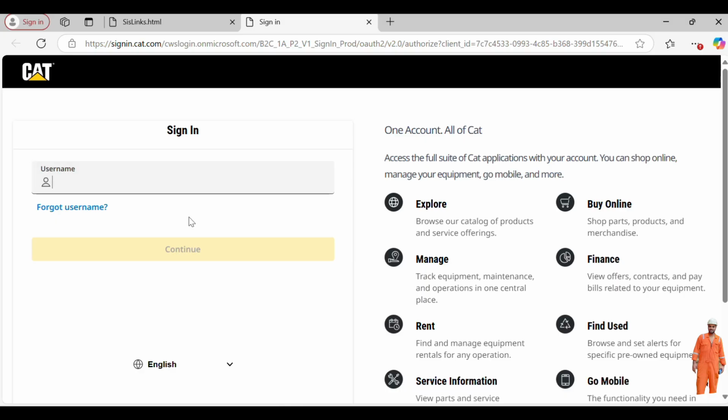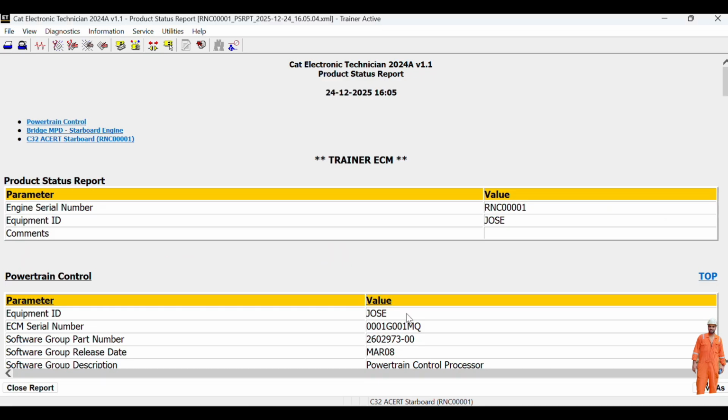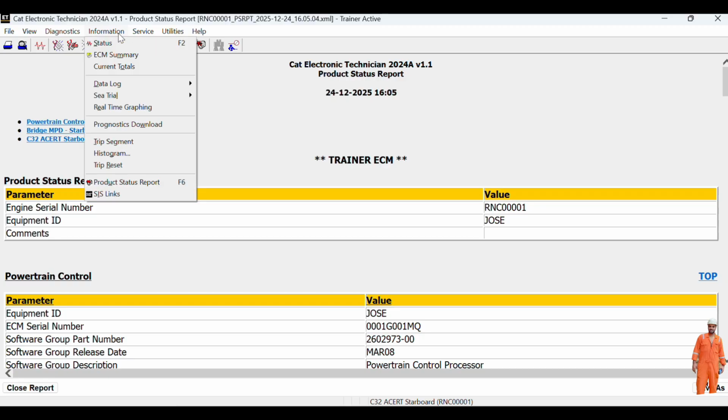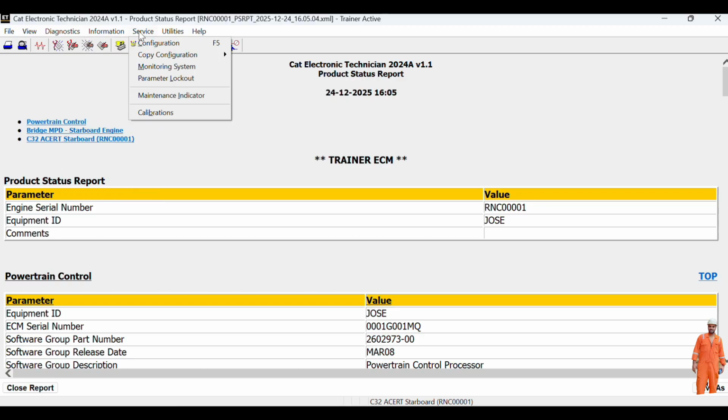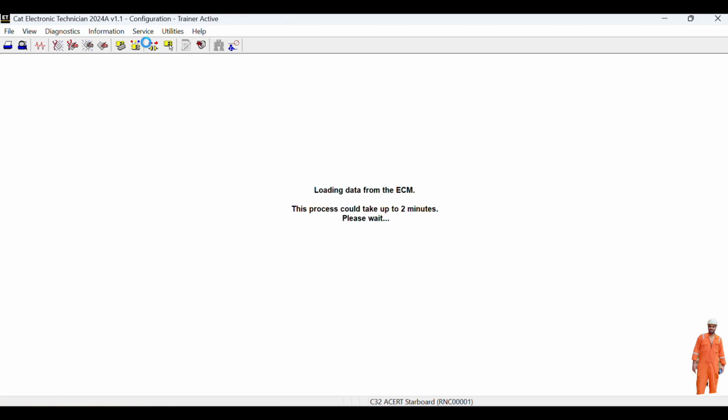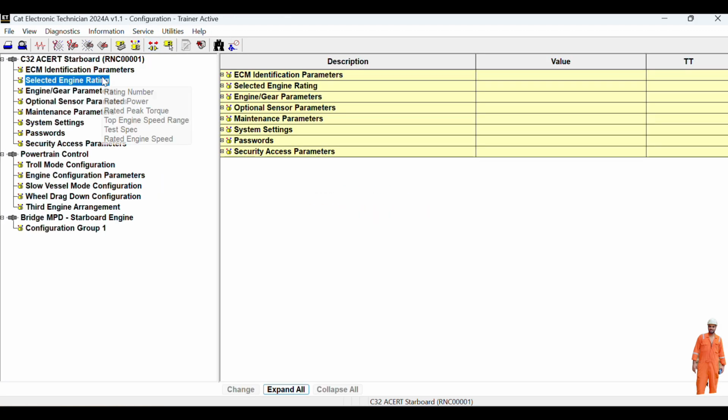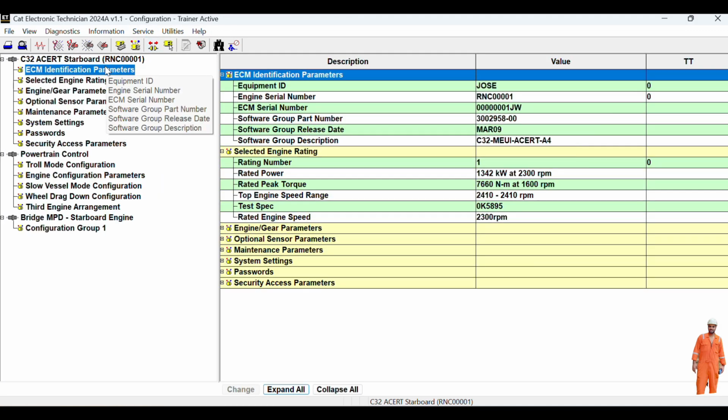If you have any problem, you see the firmware and update it, so it can be downloaded from this. So whenever you're going to change the injector, I will show you. You have to download the trim file through the syslink, save it to the local desktop and program it in your injector. Done with the information, you come to the service.